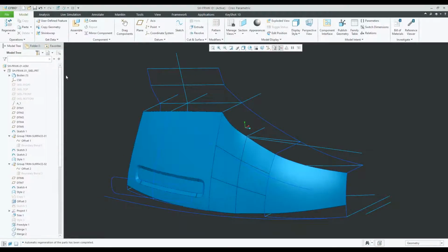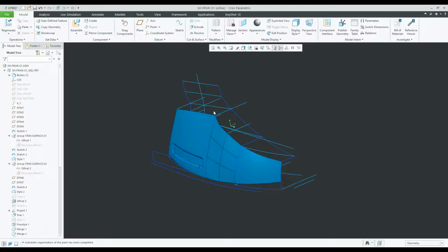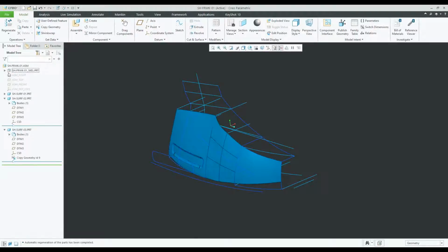So if you take the time to lay out your skeleton framework here, create all of your sketches, create all of your curves and surfaces, and get everything in here the way you want it, you can use this skeleton model to drive these changes or to drive the development of these different parts. Okay.